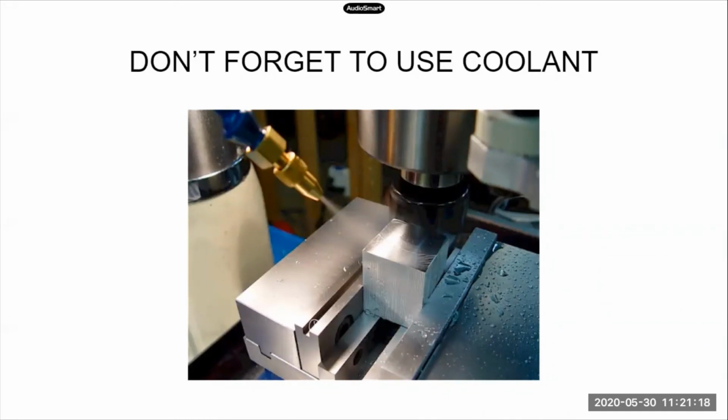As I said before, when you're designing, material selection is very important. Not only do you want to design for the part that you're making, but you also want to keep in mind somebody's going to have to make this. I should not throw an Inconel part at them unless I have to, because it is going to get really hot. They're going to have to go through a lot of tooling bits. Some tools have replaceable heads at the end of them, so you could go through those potentially fast. Do you guys have any questions?